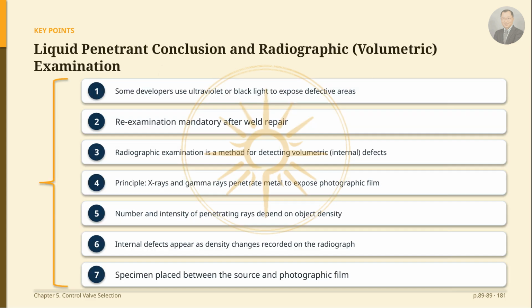I will conclude the liquid penetrant examination and introduce radiographic volumetric examination. In liquid penetrant testing, some developers require the use of an ultraviolet or black light to expose defective areas. If defects are discovered and repaired by welding, the piece must be re-examined after repair.